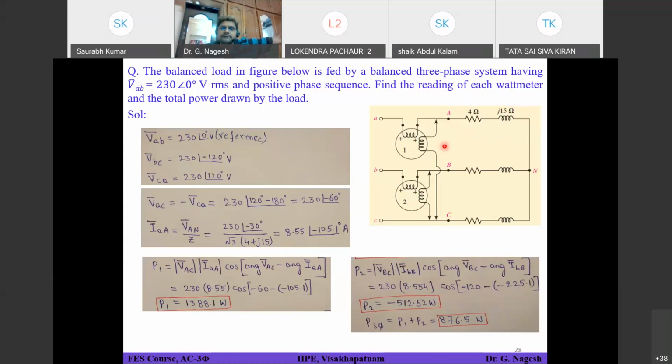Okay. We have already drawn this in the past also, that circuit, right? Phasor diagram. R will be on the real axis and X will be on the imaginary axis and Z will be root of R square plus X square, right? So try to calculate R and Z, then find out cos theta is R by Z. Calculate that value.